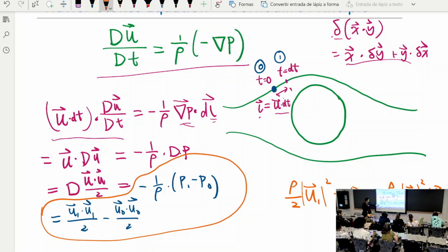It is useful because if we can compute the velocity distribution just outside of the cylinder or an airfoil or any shape, we know the pressure distribution. Actually, the faster the velocity is, the lower the pressure is. And we just said along the cylinder, for example, the flow is 0 velocity here and the maximum velocity here, which means the pressure is going to be smallest or highest here?